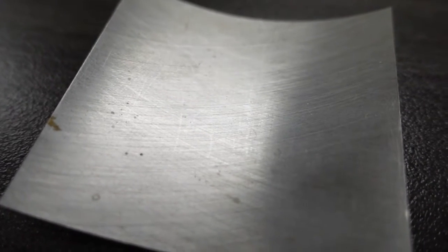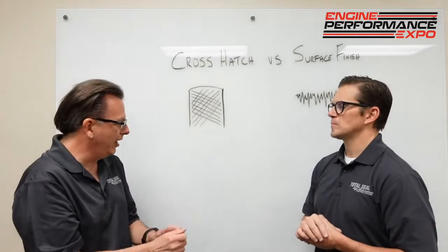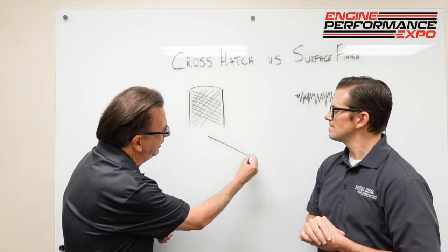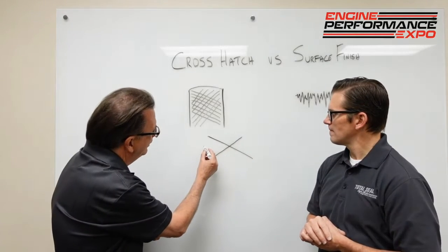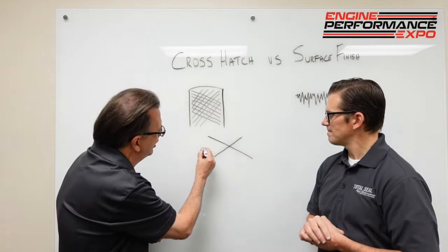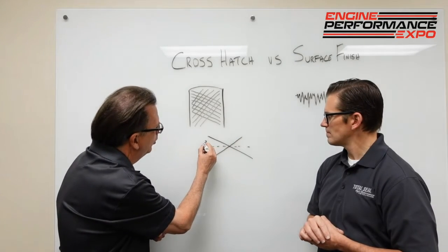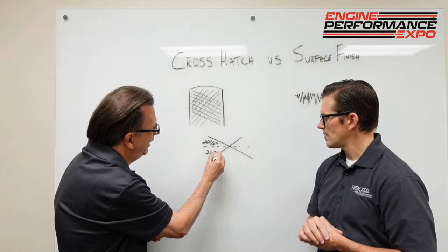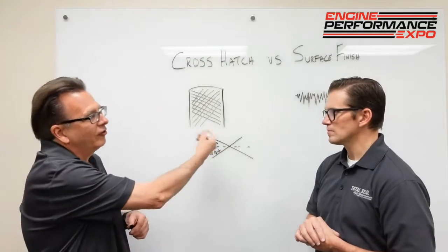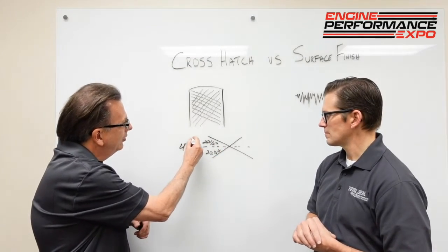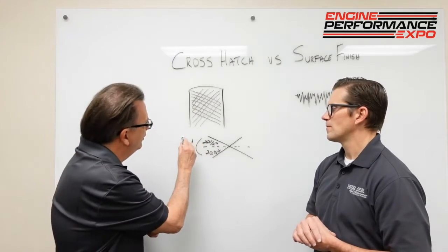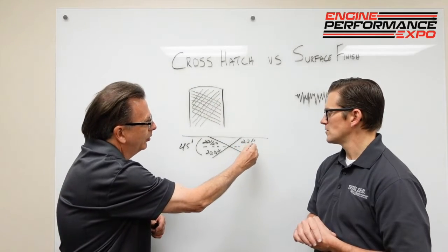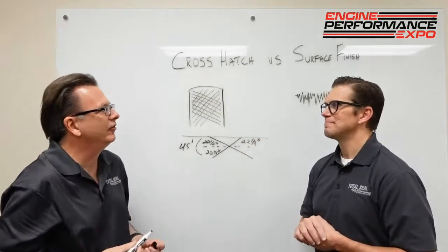Yep. So we've heard the words 45-degree crosshatch angle, very common number, but what some people don't understand is that is what is known as the included angle. If we draw here's your two crosshatch cuts, and an imaginary line through the middle, we're 22.5 going up, 22.5 going down. That's our 45-degree crosshatch angle. Or, if you measure it simply off the top surface, the deck, you'd be coming down 22.5 degrees. Right. That's how you define your crosshatch angle.